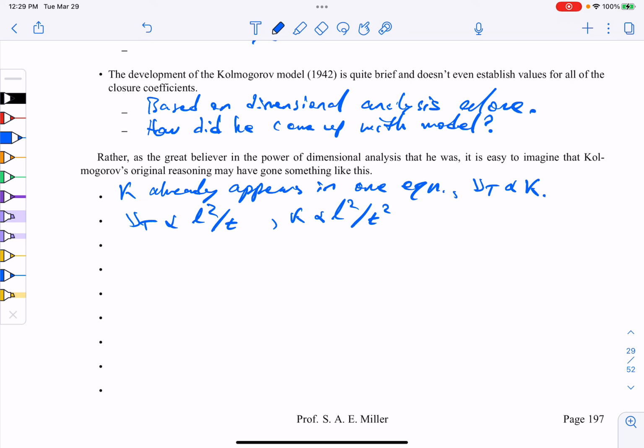So what would the dimensions of eddy viscosity by k be? Let's look at our dimensions. The length squares cancel, and that's 1 over time over time squared, so I think that goes as time. Okay, now what about turbulence dissipation? Turbulence dissipation is another dimensional variable, and should go as length squared divided by time cubed.